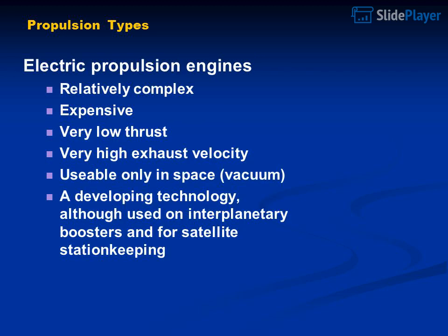Electric propulsion engines. Relatively complex. Expensive. Very low thrust. Very high exhaust velocity. Usable only in space, vacuum. A developing technology, although used on interplanetary boosters and for satellite station keeping.